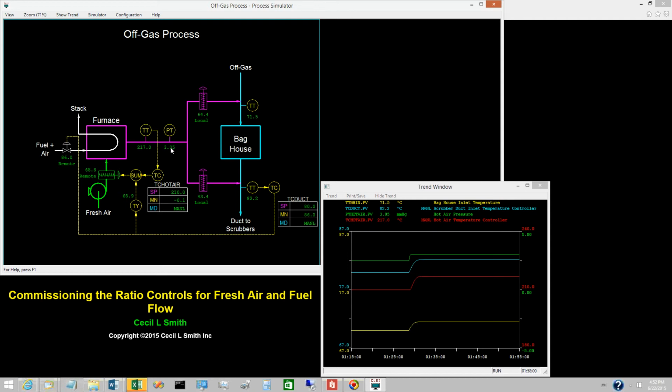To maintain a constant hot air pressure, any change in the opening of the fresh air damper must be accompanied by a change in the opening of either or both of the hot air dampers. One possibility is to develop additional characterization functions that relate the hot air damper openings to the fresh air damper opening. The alternative is to provide a control loop for the hot air pressure. As the hot air pressure responds very rapidly, a control loop is the preferred approach. We shall propose one in a subsequent video.